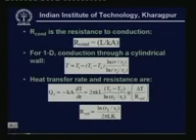Now, this conduction resistance is given by R conduction equals L by kA. That means it is a function of the geometry of the system and also the property of the system, that is thermal conductivity. And you can also derive this one-dimensional steady-state heat conduction equation for a cylindrical wall.